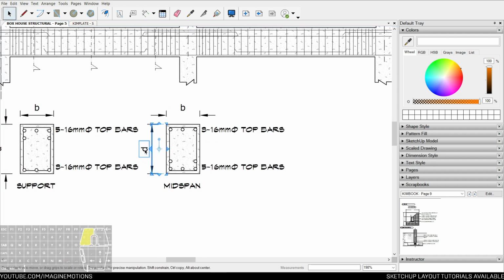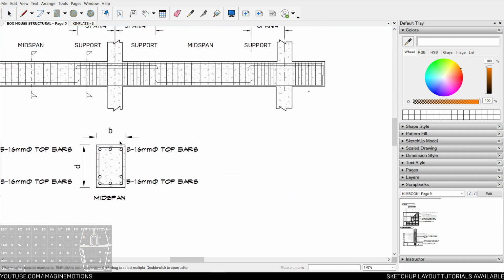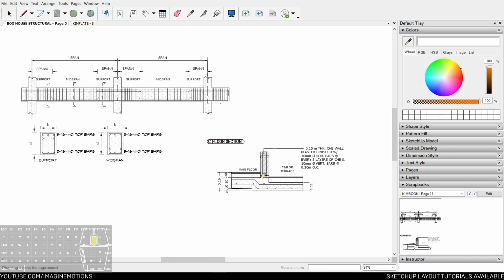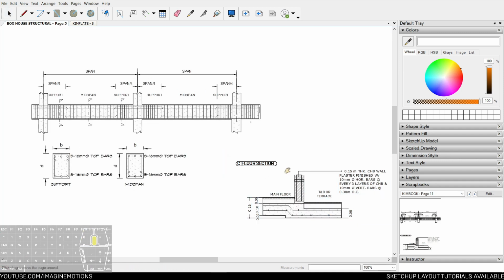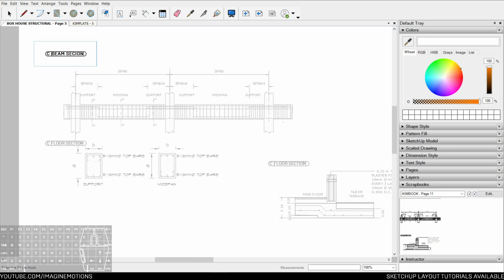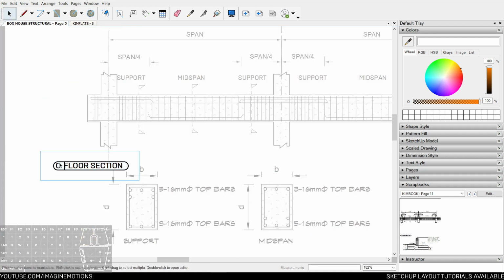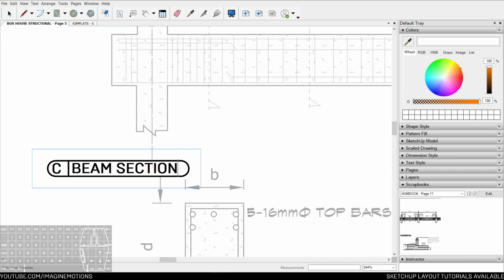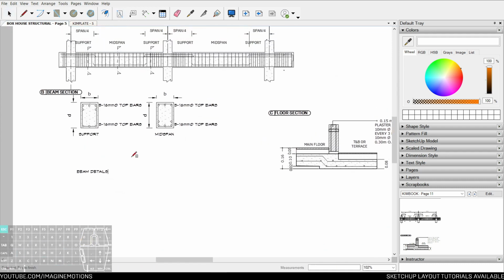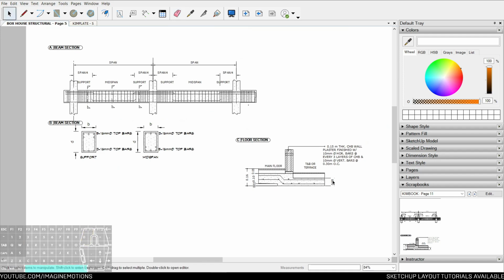If you put this to scale, then this can actually have its own dimension. But as I said, if there's no scale, just place a schedule tag. We'll see our floor section now. You can actually use this to label like that. You can put beam section A. Well, that's also section B. And your title could be like beam details. So this is what you put in your drawing number. You don't have to put 1, 2, 3. It's gonna take so much time.